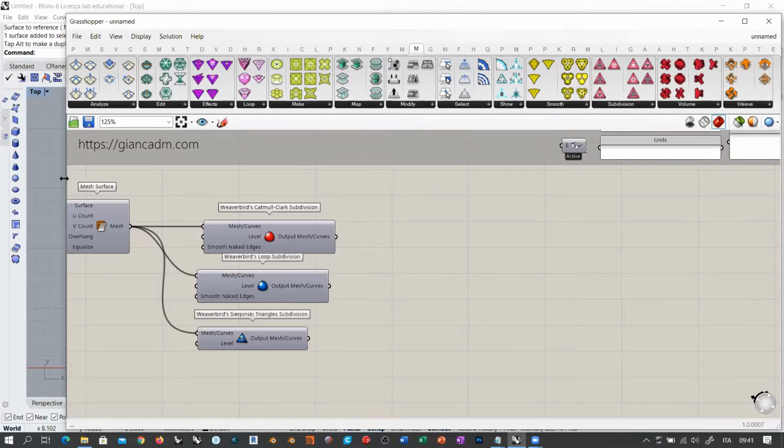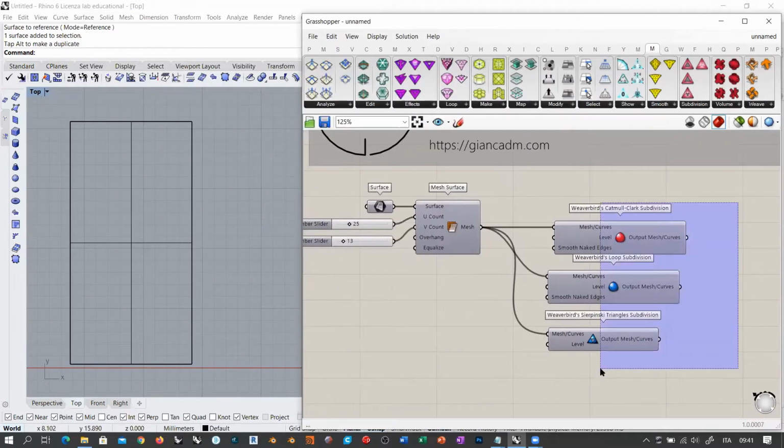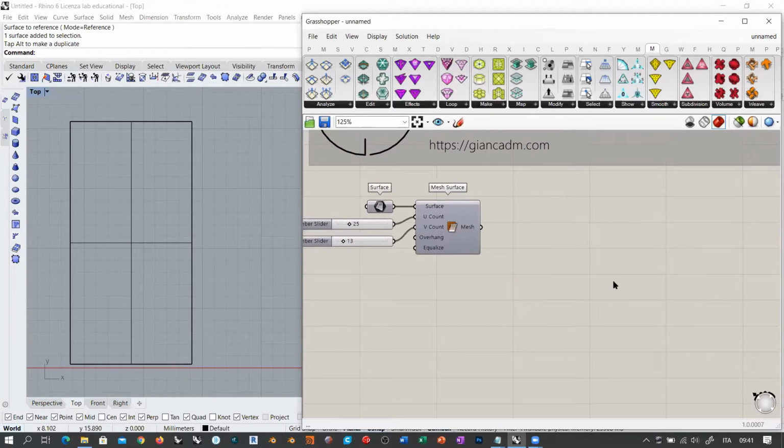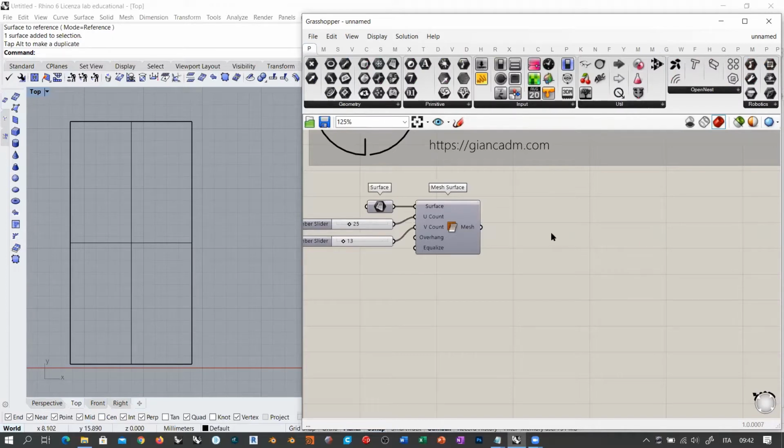What's the problem with all this Rhino Grasshopper workflow, with or without plugins? The problem is that you have no control over the resulting topology. You cannot define the topology, let's say, by hand. Like, I want this topology to run in a particular way along the body of the mesh. You cannot do this because all of these tools are somehow semi-automatic. So you can achieve interesting results, but you have no control over the real topology that we need for our